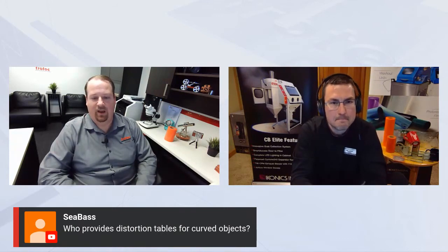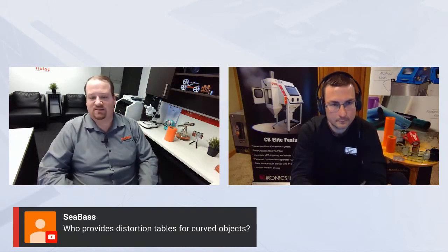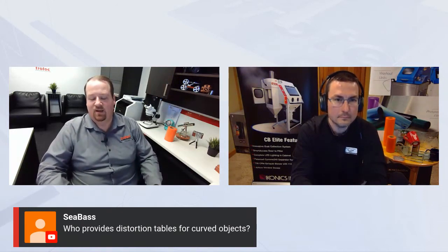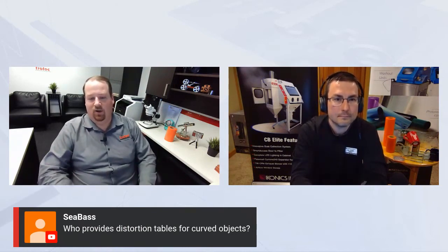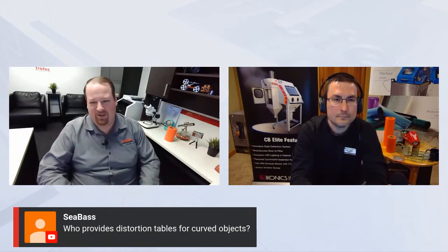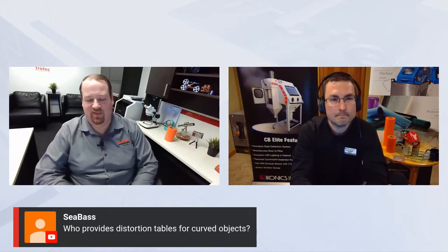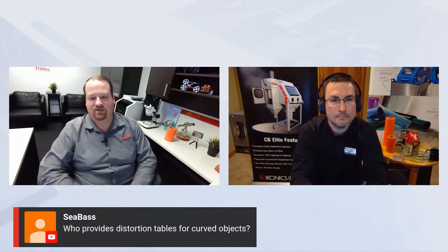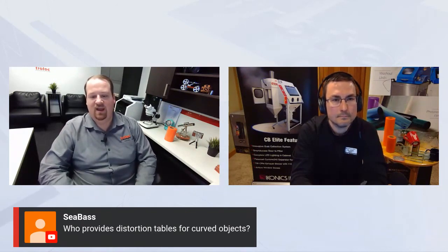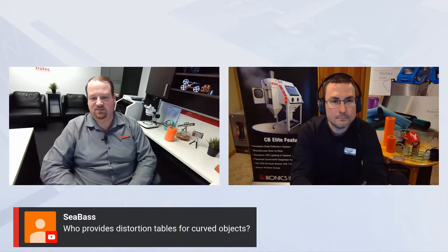No. I don't really use a lot of that because with the laser we will actually place the mask over the surface of something like a cup, for example, and then we will rotate that cup so that there is no distortion needed. All compensation is done in the laser automatically. If you're putting it on and doing it before and then applying the mask, maybe you would have that problem. But the laser compensates for that by rotating around an object, giving you any compensation for radius distortion.